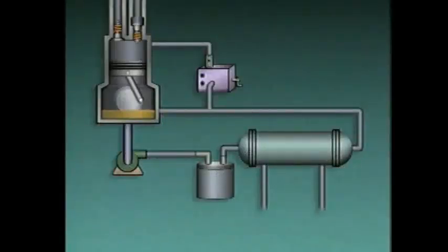Compressed gas systems use auxiliary devices to remove oil or moisture from compressed gas and to prevent overpressurization. Two devices that are used to remove liquids from compressed gas are oil separators and demisters. Most reciprocating compressors that contain pistons use oil to lubricate the piston rings.